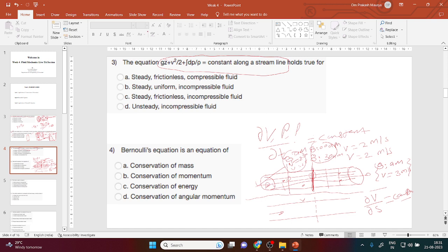One question, sir. In case of steady flow, the measurement will be from only one particular spot, while in case of uniform, it will be throughout the channel? No, in case of steady flow, you can check at another section also, but your velocity may be different at another section.